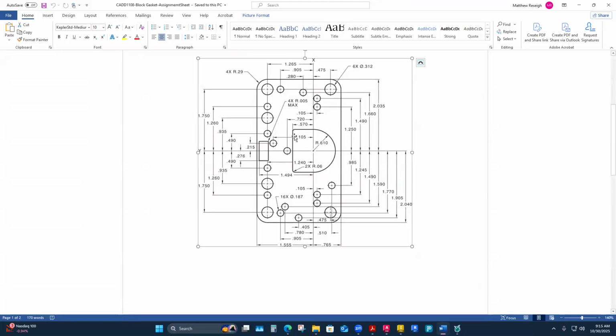But I'll draw it that way, and then if I was the drafter, here's the way I think too: sometimes I would come across something that I've got a lot of data for from an engineer, right? They've given me a lot of work to start, so I'm gonna go to town working on this. Yes, I might come across a few questions. I'm just gonna make note of those as I draw. I might draw them in thinking, well, it doesn't say it's different, so I'll put it in symmetrical, but I'll make a little note to myself. I'm going to ask the engineer before I lock this down if that's symmetrical there, or I'm going to have to go reference a model what this fits to or something.